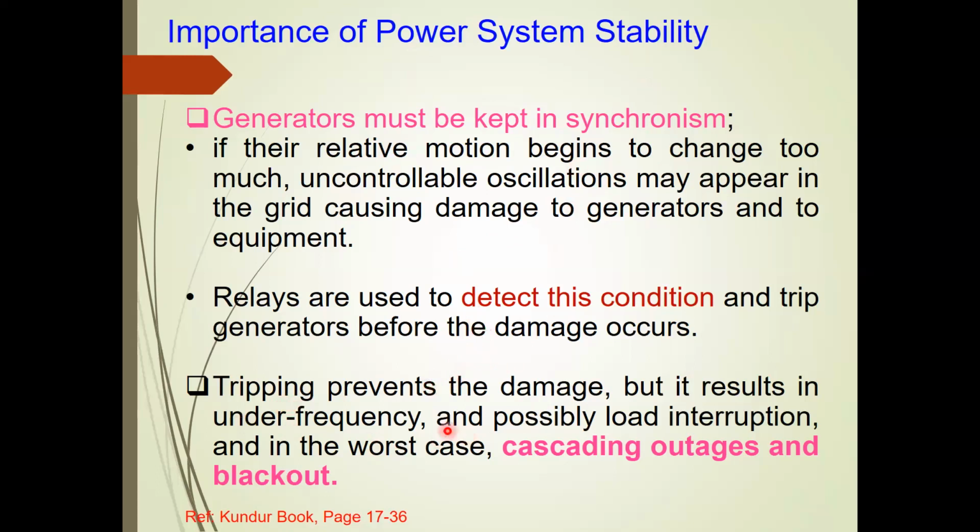Okay. It is very obvious that if you are not able to maintain the balance between the generation and the demand, under frequency will be observed in the signal. If this scenario is observed, say you have a generator outage and you are not able to meet your demand, you want a match between generation and demand, so you can argue: why not interrupt the load? That means you disconnect the load.